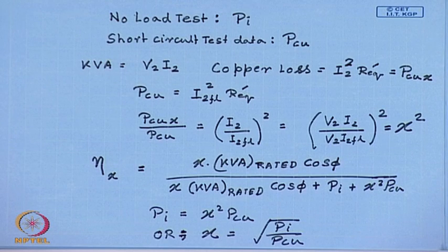From this discussion, we also can conclude one more thing, that getting the transformer efficiency at a particular load does not give the full picture, because the loading of a transformer can vary over a day. Normally, it is expected that the loading pattern of a transformer will repeat over every day in a season at least.